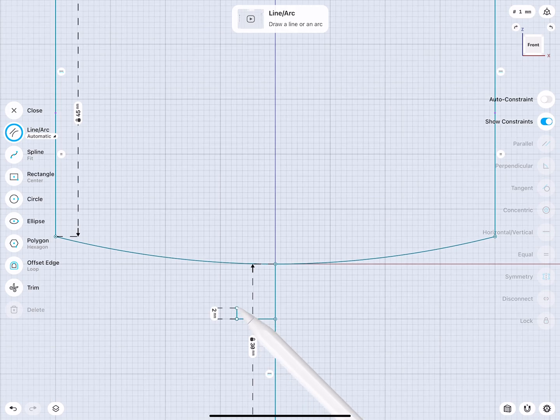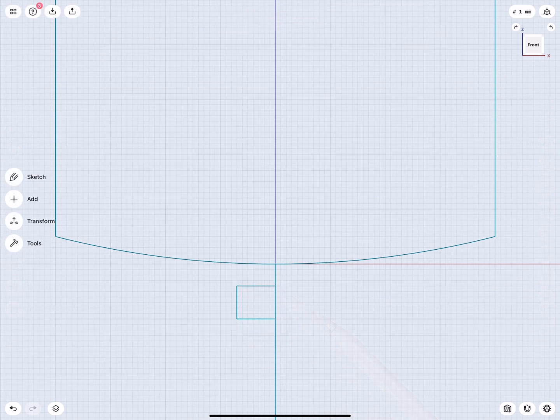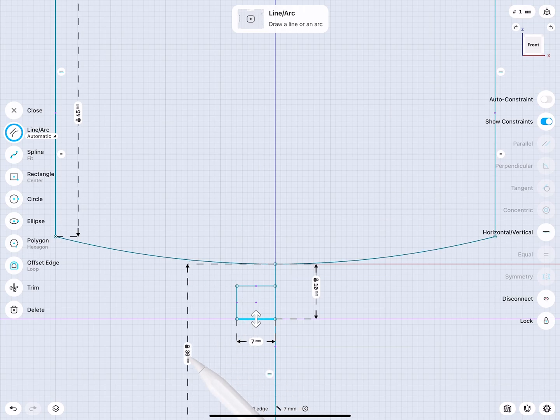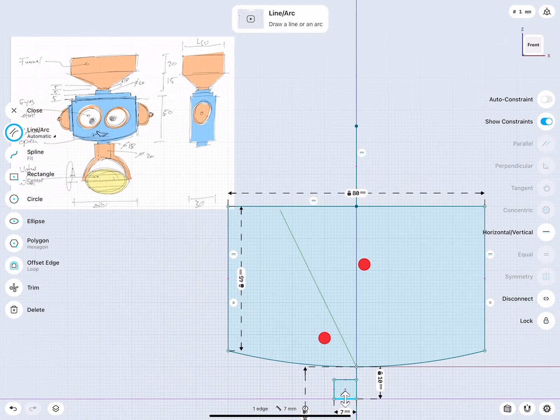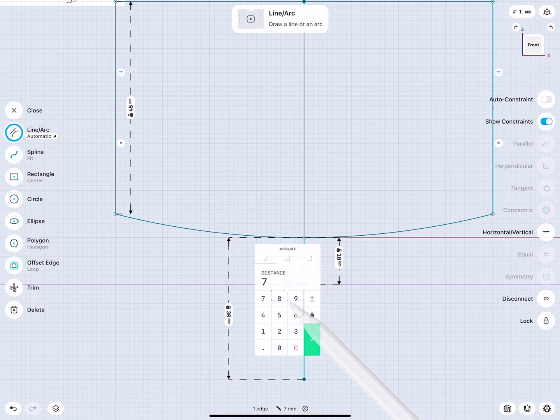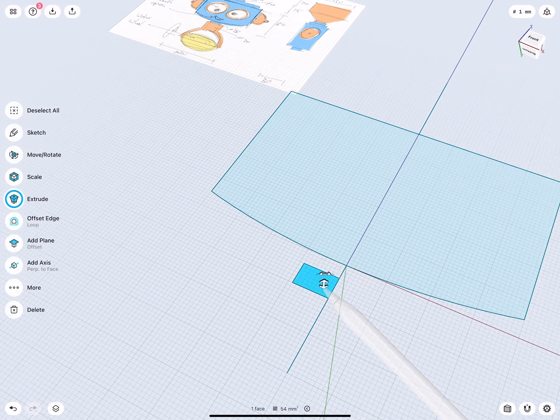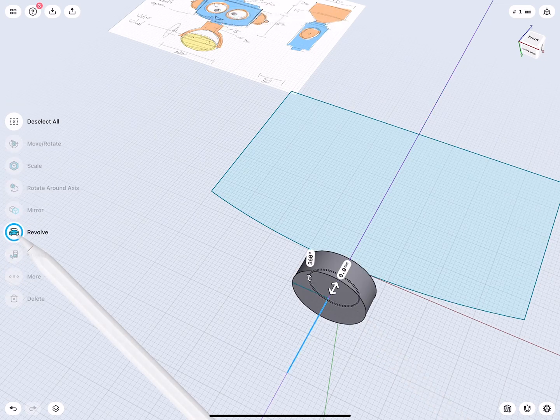So we'll draw a line, draw a line, draw a line. From here to here, what is the height? This is 10 millimeters, so a centimeter. And this, now we can think about it. Is this good? Yeah, 10 millimeters looks good. Very nice. The distance, this should be 18. So here the radius has to be 9. So here and here, there we can make a revolve object.